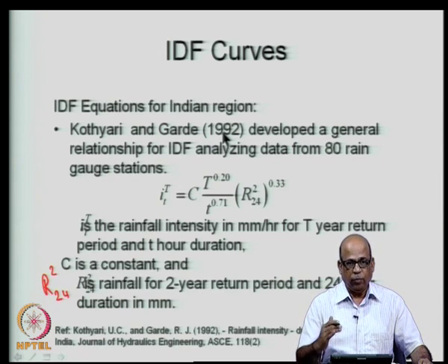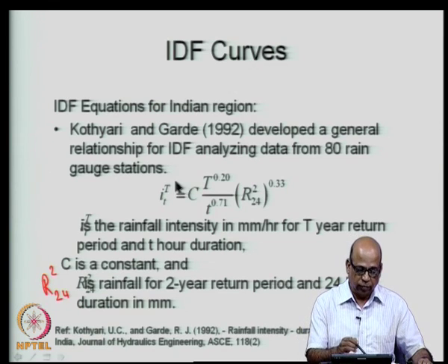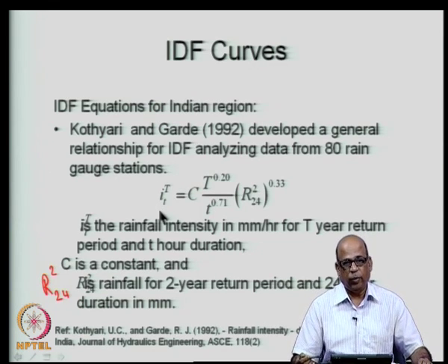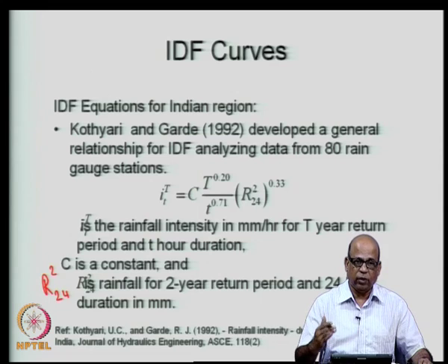So, as time progresses, your relationships may become different, and therefore, the intensities that you may have to use in hydrologic designs can be different. This means that there is some non-stationarity in the IDF relationships themselves. That means they do not remain stationary.